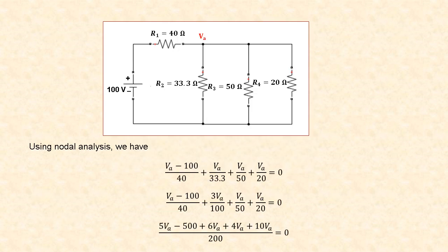We shall solve this problem using nodal analysis method. In this circuit there are only two principal nodes and let us consider the bottom node is grounded, that is the reference node, and the top node is A. The voltage at this terminal is VA. We have to assume that this voltage is superior to all other voltages.